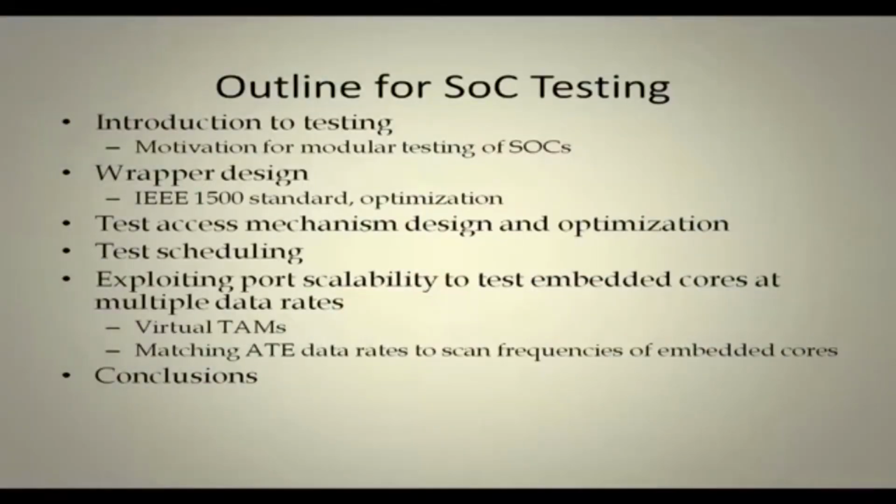So, this SOC testing, we will go like this. We will cover the motivation for modular testing of SOC, then look into wrapper design, the IEEE 1500 standard and optimization, test access mechanism design, and test scheduling. These are the various problems. Wrapper design is an important problem.